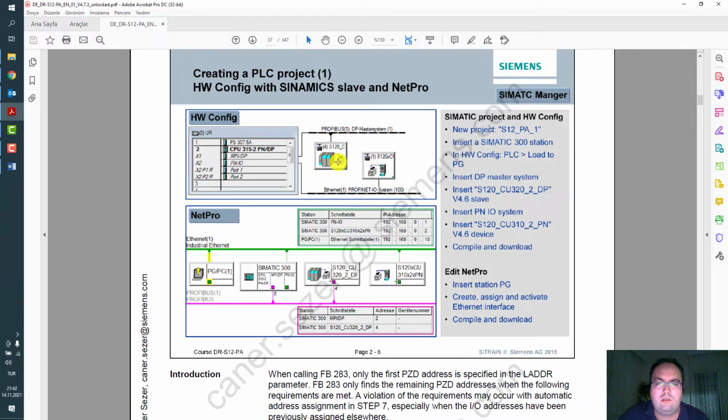It's a multi-axis. It's important to know that if you are using Profibus, the baud rate and the device address are important. On PROFINET, the IP address and the device name of the device are important. To set up the communication, you have to check the settings both on the PLC side and the drive side.